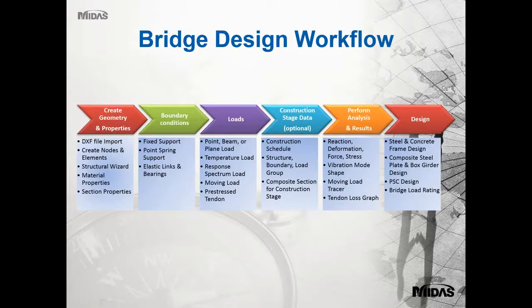Then we perform the analysis and review the results, which include your reactions, stresses, beam forces, and deformations. And then we finally do the member design check within the software. We have steel and concrete frame design, composite steel plate and box girder design, PSC design, and we can also do rating design.